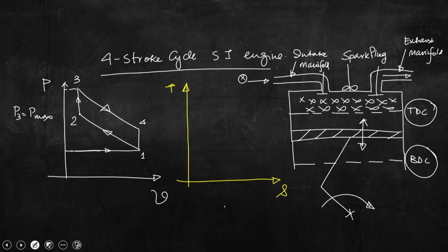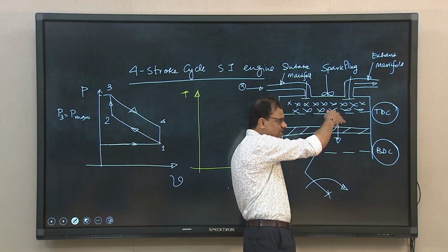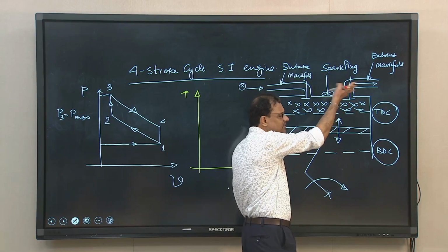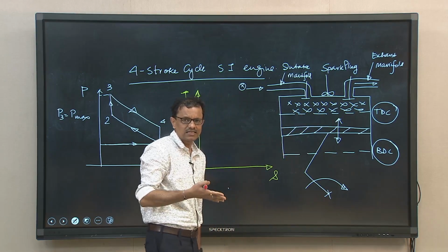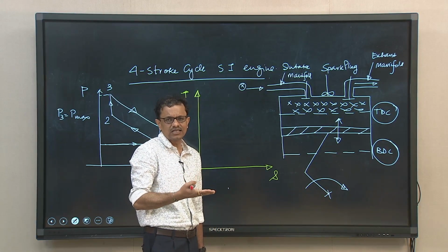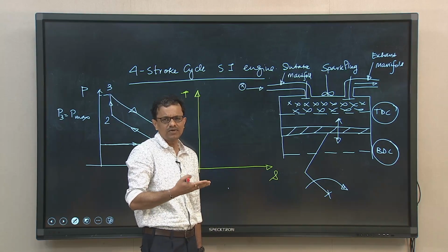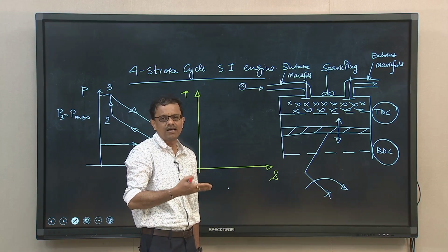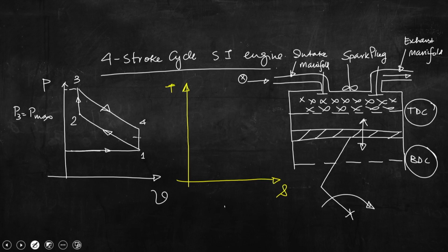As the piston is exactly at BDC, when we open the exhaust valve, the high pressure inside the cylinder allows the combustion gases to leave, and there is mass loss, and that mass of combustion gases carries some enthalpy. So, that is heat loss. This is Q out. I am writing in terms of specific quantities, and this combustion is Q in, heat addition, which you have studied.